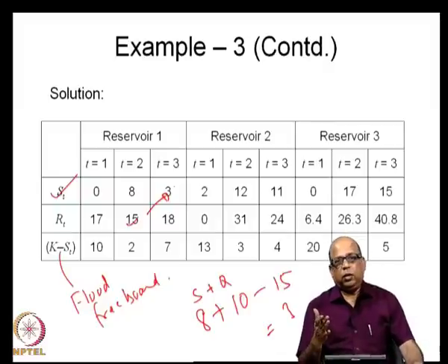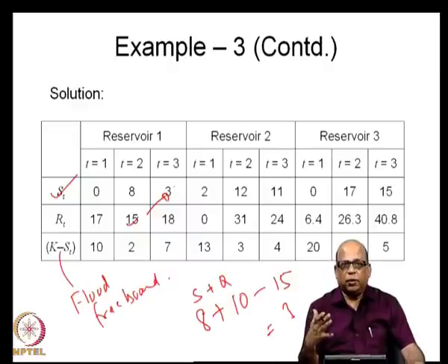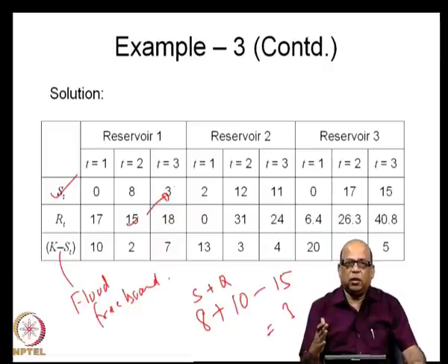So, the storage continuity, that is the mass balance, has to be maintained even in the optimal solution, and in general when you have large number of constraints, large number of reservoirs and so on, it is better to put a check on the final optimal solution that you obtain to ensure that the mass balance is in fact maintained in the optimal solution. Why this is important is because of the overflows. Overflows in general as equality constraints cause some difficulty in large linear programming problems.